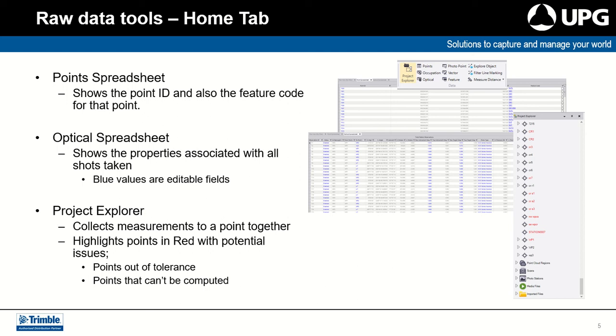You can select an individual field and edit that information, or you can group select it in this window by using the dark grey column right at the very left-hand side. You would just select the first row that you want and then hold Shift and go down to the row that you're wanting to edit. Then to edit that group that you have selected, I would open up the Properties window and make the edits within the Properties window.